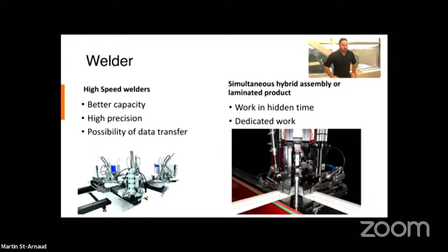High precision, where am I going with that? So if you're thinking about a 1,000 millimeters or 1 meter frame or sash, you're going to be cutting it a little bit longer, so to 1,006 millimeters, burning 3 millimeters on each side, and then you're going to have your 1,000 by 1,000 at the end. But for all the good reasons, you could be having problems with your saw. You're cutting too high or too low.